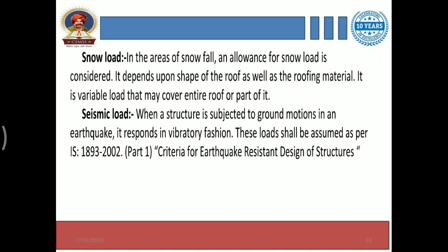Okay. Then the last one is seismic load. When a structure is subjected to ground motions in an earthquake, it responds in vibratory fashion, and this load shall be assumed as per IS 1893 2002 part 1, and the title of that IS code is criteria for earthquake resistant design of structures.